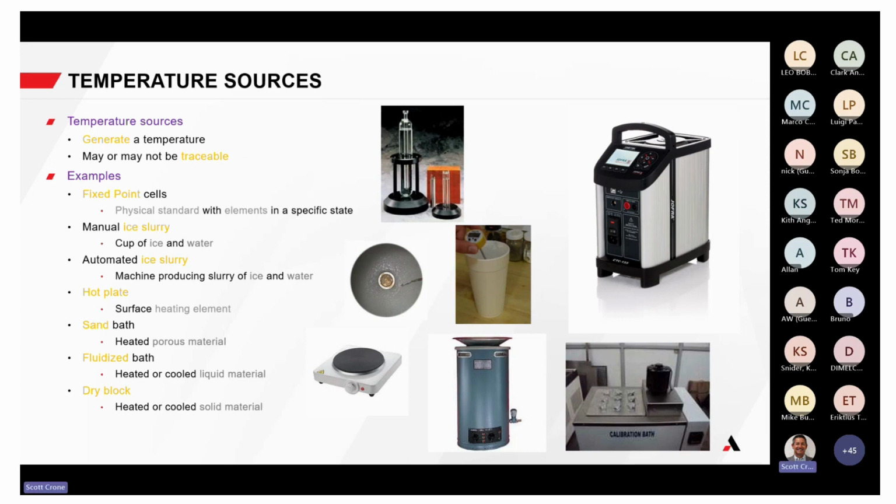One of the other technologies used as a heat source is a sand bath. These use some exotic materials in a porous or sand-like consistency, and you'll stick the element in there, and they heat up to a certain point. Those were pretty common because they were a little bit easier to move than liquid baths. But the problem is they're very slow. It takes a lot of time to get from one temperature to another and to let it stabilize. Once it's stable, it hangs on pretty well as long as you get the gradient and have a reference in there. But they do take a lot of time.